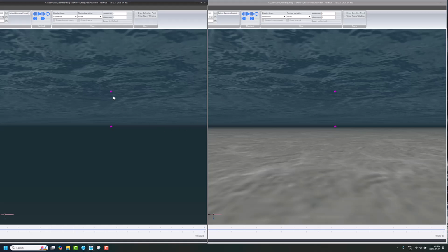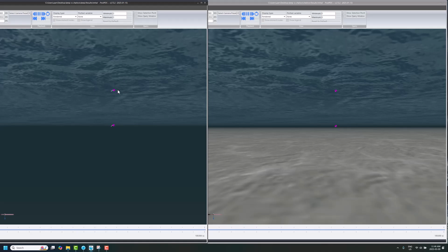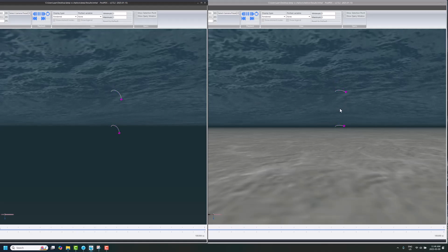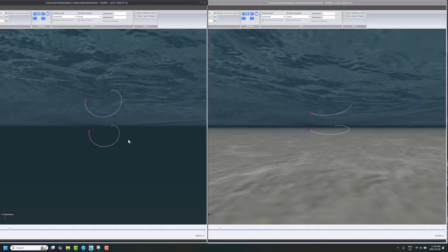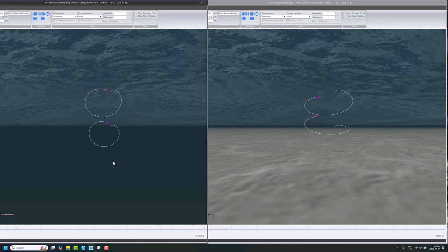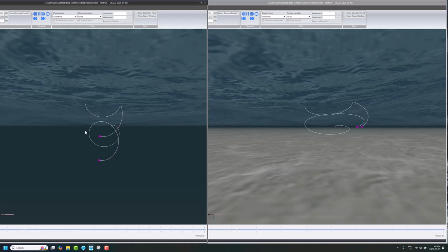Maybe you're wondering, why didn't you use a point mass? Well, we totally could have. There's a great feature in Proteus where we can show the position history, so you'll see the tails, which really illustrates what's happening. It doesn't do that with point masses. So we'll play these two cases, and you see the waves ramping up and we start seeing the position history. Ultimately, in deep water you get much more circular patterns of the wave particle velocities, and that creates motion and drag loads on moorings and anything floating in the water.